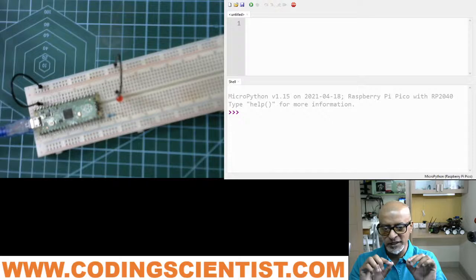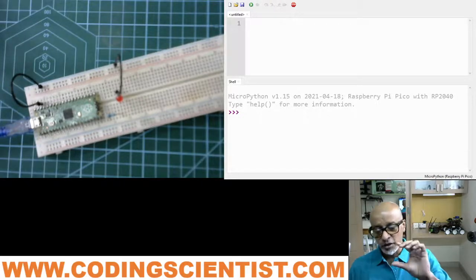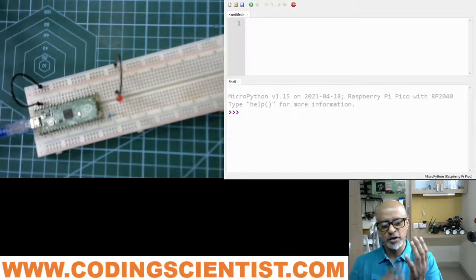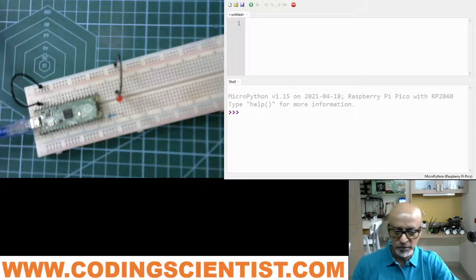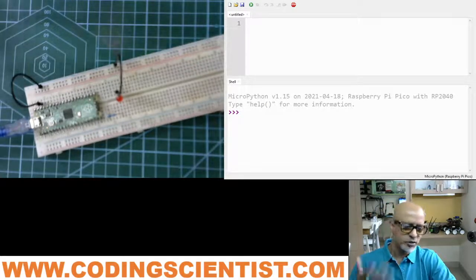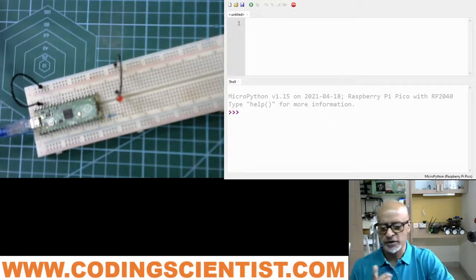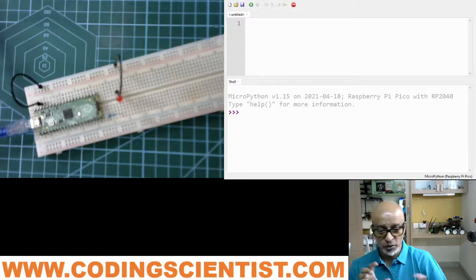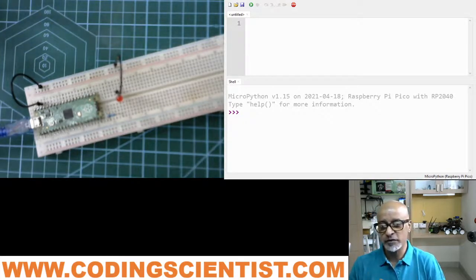You can grab one of those and keep it. With that you can see the pin drawings, or you can just tilt your Pico around and see the pin numbers. So I use pin number 15, and you may use different pin numbers as you wish, but make sure that in the MicroPython code which we are going to write now in the IDE, you change the pin number accordingly. Alright guys, so let's take a look now.